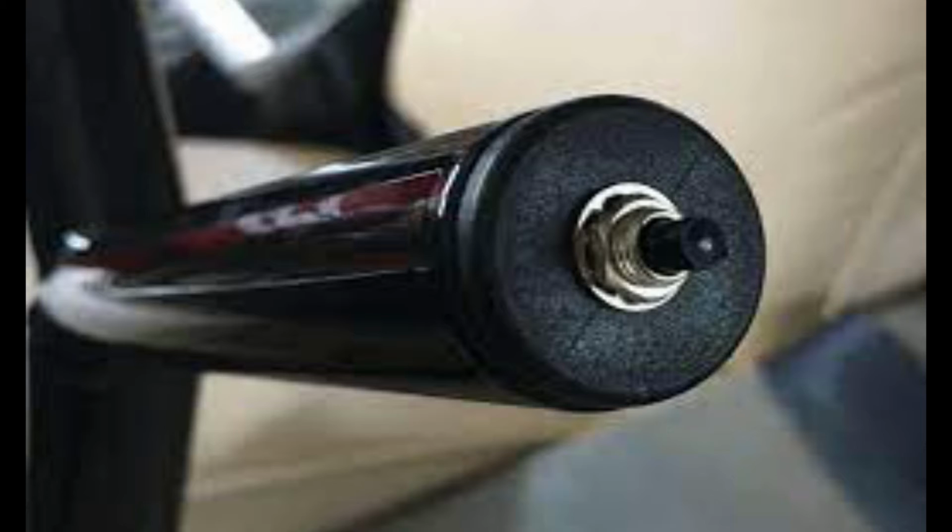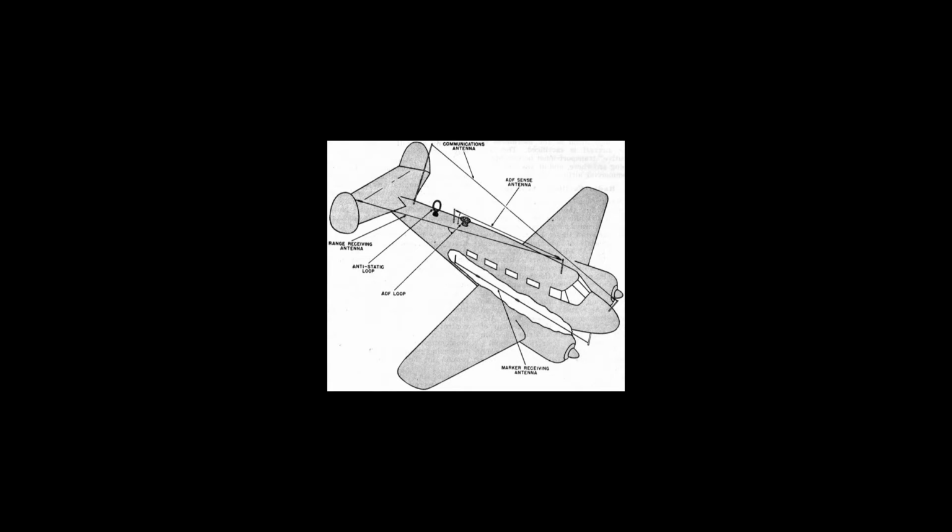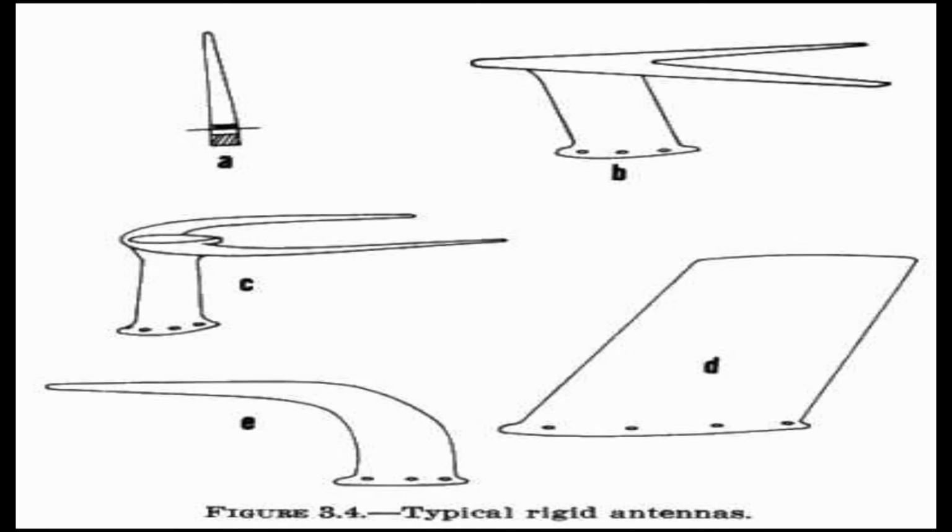Antennas. Antennas are conductors that are used to transmit and receive radio frequency waves. Although the airframe technician has limited duties in relation to maintaining and repairing avionics, it is the responsibility of the technician to install, inspect, repair, and maintain aircraft radio antennas. Three characteristics are a major concern when considering antennas: length, polarization, and directivity. The exact shape and material of which the antenna is made can alter the transmitting and receiving characteristics.